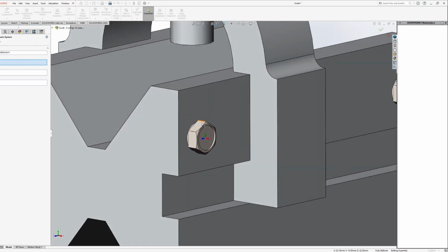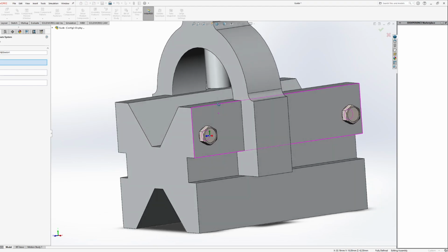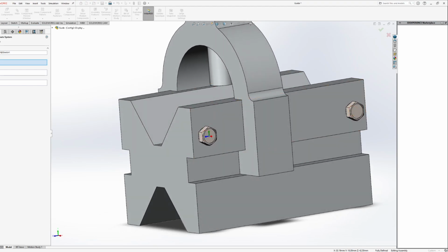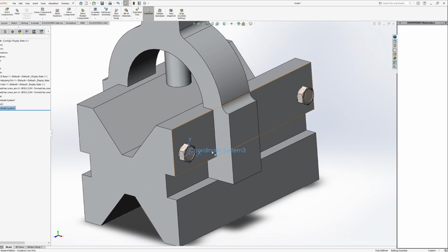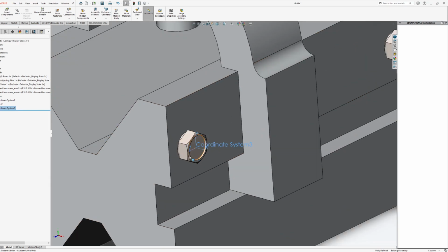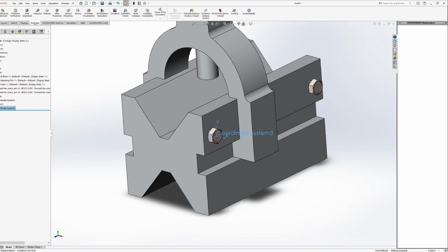So it is referencing that specific point now. And sure, I don't really care about the axes. They should all be either what I want or really nothing that's too crazy or straying from the norm. And now I have a coordinate system that is based right on that point itself. And just as what I would normally do, I can go into the mass properties and use that as the location of where I'm referencing the center of mass.